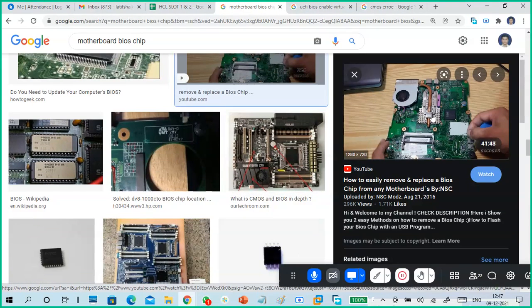The CPU is here, and this is the fan assembly, the heatsink assembly. If you see the copper rod here, your CPU gets heated, so it absorbs the heat and passes the heat to this fan assembly, and it will go outside like this, not upwards, not downwards. Usually the heat will go out the side of the laptop.